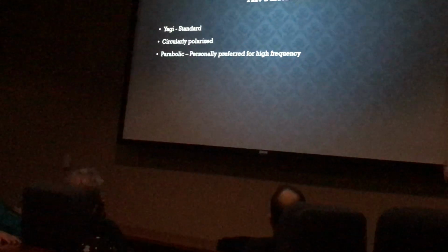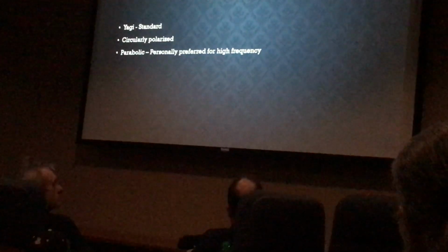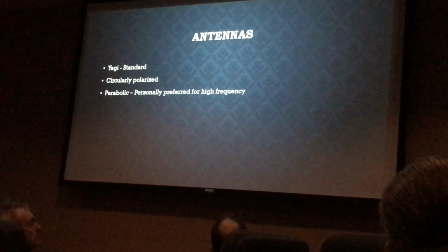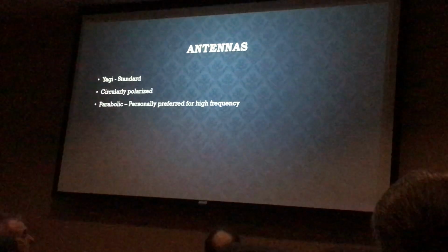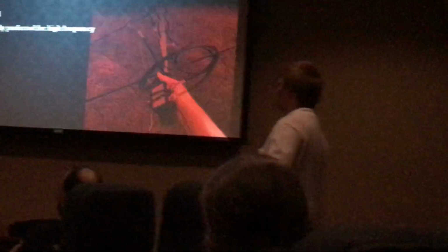And as far as a parabolic dish, it would definitely be pretty nice to be able to use a parabolic antenna, but to build a parabolic at 2 meters or 70 centimeters, you'd have to have a pretty big dish compared to the same gain you get from a Yagi at that low of a frequency. So the parabolics I usually only use above 1 gigahertz depending on what I'm doing.